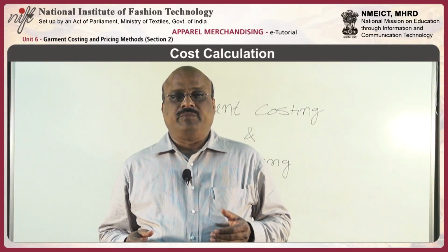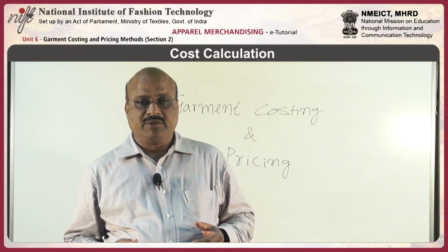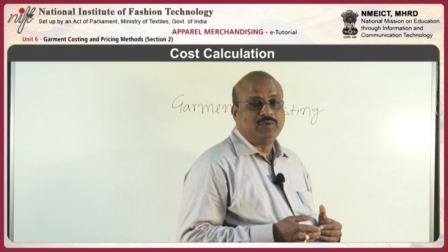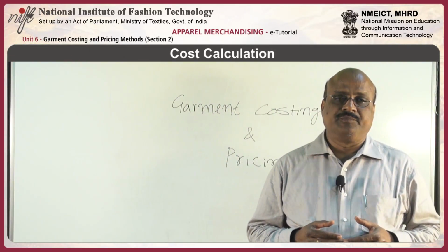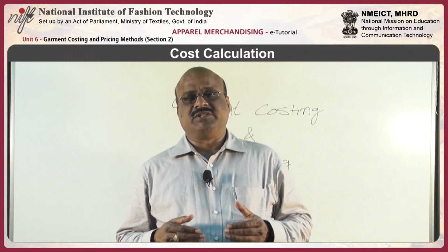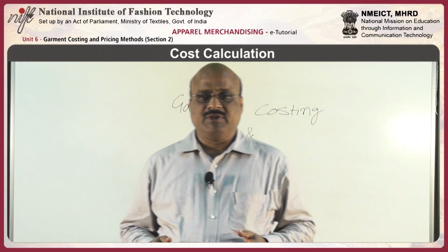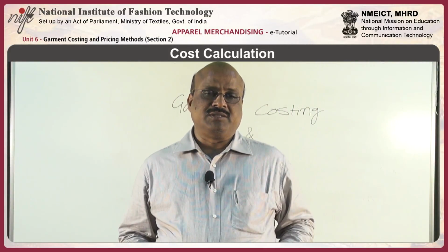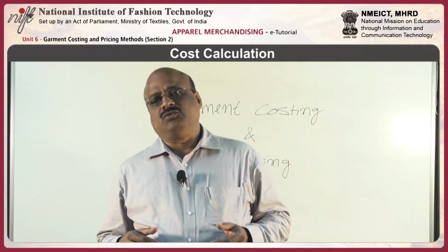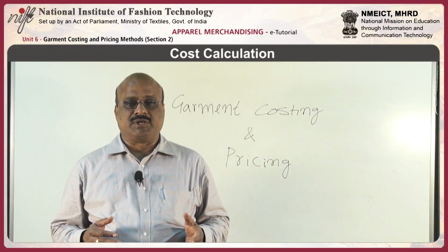So in order to maintain the inventory and to avoid shortage during production, fabric wastage percentages are to be added while calculating the fabric consumption. We should always take into consideration a certain amount of wastage that is possible while making the garments, because it is not easy to source the fabric, and we may not be able to source the fabric all of a sudden.